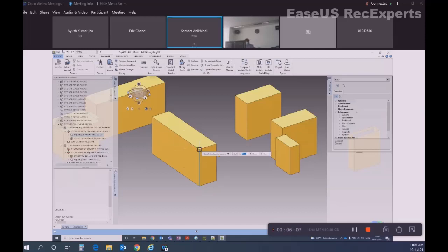Click here, and as soon as I press first point, the text inside the polygon is now relative. So that means whatever second point I select, the coordinate of the point is with respect to the previous point, right?